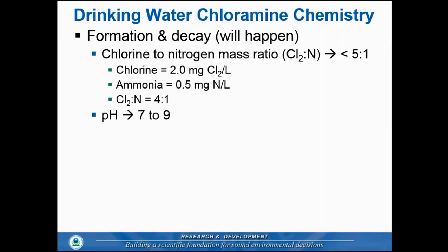Beyond these two things, there's a couple other items that are also very important, and that is how well the chemicals are mixed when they're added to the water. What you don't want is localized concentrations of chemicals, as that's not going to do you any benefit. It's going to cause you to have concentration gradients that can also affect the pH, so you can form things you don't want to form.